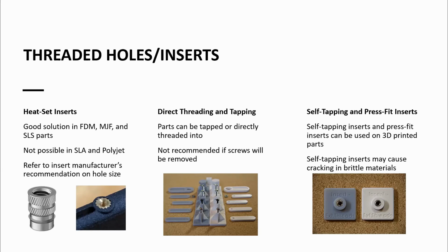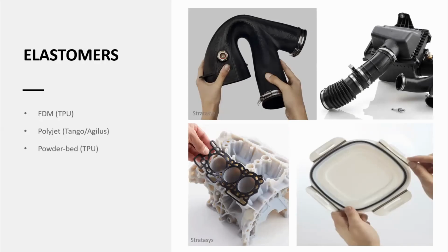However, self-tapping and press fit inserts could be a good choice for any material. It's important to consider with self-tapping inserts, as well as directly inserting fasteners in parts, that brittle materials might be more prone to cracking. Elastomers are also something that we have access to with additive manufacturing.